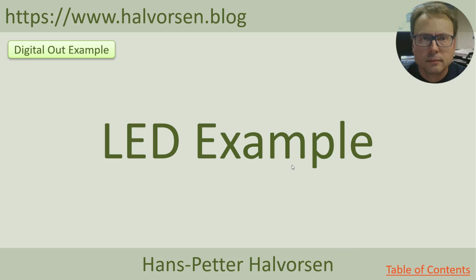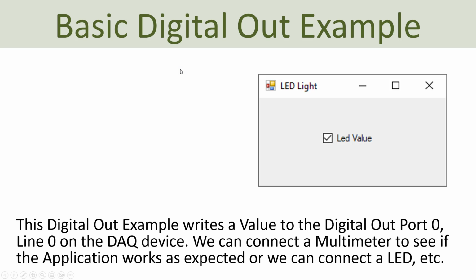So the next example is a basic LED example. Here we will use the digital channels, in this case digital output. So basically in this example we will connect or wire a LED on the breadboard, and then connect the LED to the digital output channel on the DAQ device.